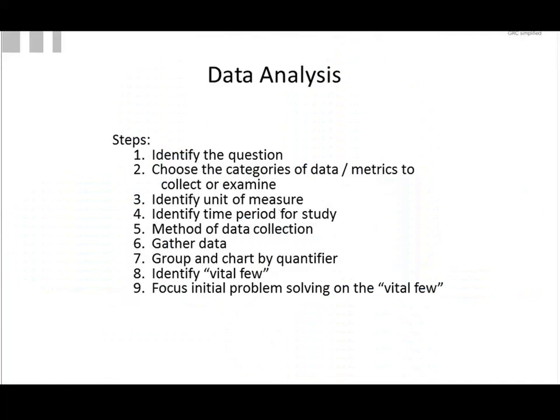And of course, in analyzing the actual metrics that you're selecting, you want to tie it into what question you're trying to answer by collecting this data. And then that will determine what type of data and what type of tools to measure that data you will put in place. It may be temporary, so you determine, number 4, the period of time for the study. If it's permanent, then you just put it under change control and keep it out there forever. And how you're going to collect it. It's going to be automated, it's going to be manual, it's going to be a logbook, etc. And then you gather that data.